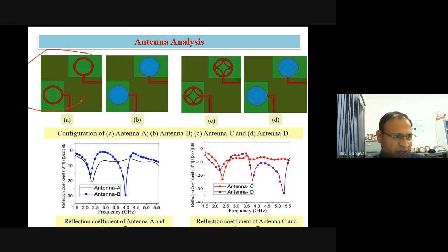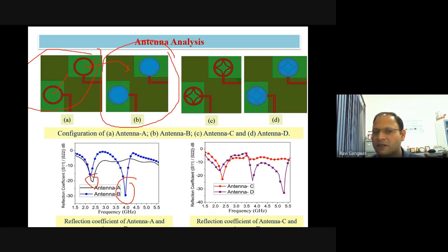First, I have taken a simple annular ring shape as the antenna, and then I have radiated it. Then I have seen that we are able to get only one peak here. That means this works as a radiator. Now, in the second case, I put a DR on the top of this particular arrangement. Then I get another peak. Now this antenna is the perfect example of the hybrid concept. That means here the excitation mechanism along with the DR both are radiating into the far field region. It means this antenna is basically a hybrid antenna.